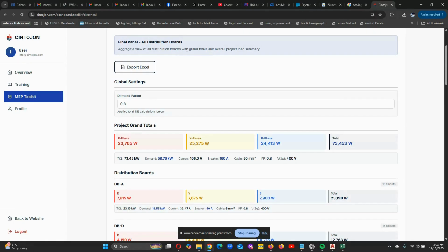You also have the plumbing design toolkit where you can size your pipes. Okay. You can look at the slope. You want to determine the slope of your sewer line, from the invert of the manhole or inspection chamber effluent to where the final manhole is before the sewage plant or the septic tank. It does that for you.